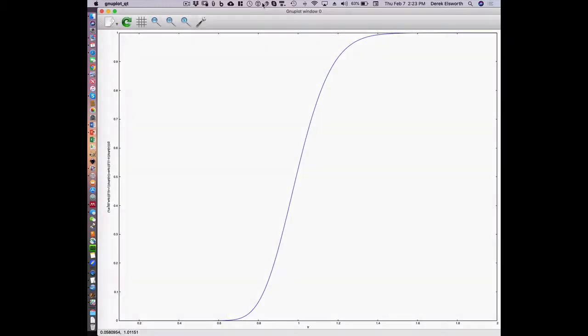So this is one pore volume, 0 pore volumes. If it was plug flow, then there'd be no concentration until all of a sudden the front arrived, and then it would go up to 1. So this is for a Peclet number of 100, a big number.